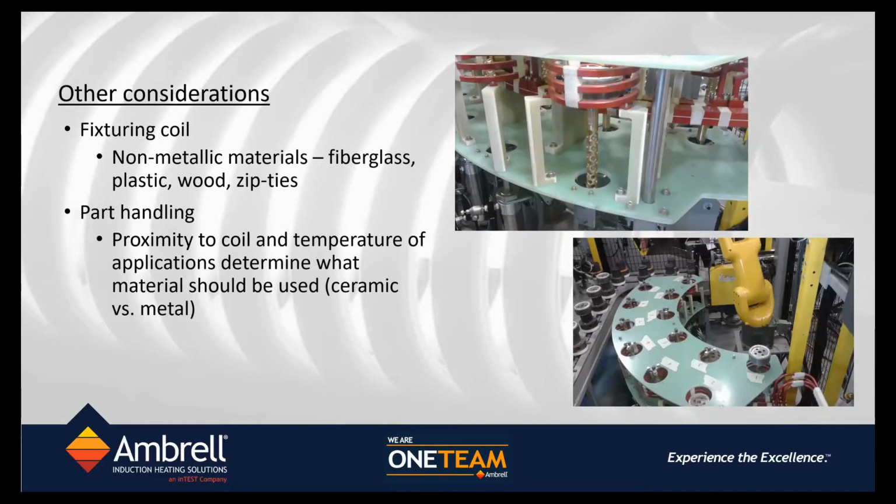In the industry also, as you are manufacturing, you know that you're going to be moving the parts in and out of induction heating coils. So the fixturing and the handling becomes really important as well. You can see the fixture that holds these parts in the picture; these are rotors for electric motors.